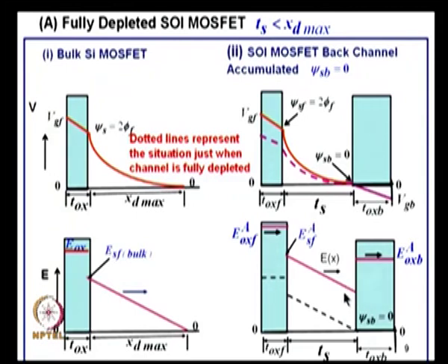I am giving the numerical number because 1000 charges here, okay, 900 charges here, 100 charges coming extra from there. Charge neutrality is maintained. So, this field is not changing, this voltage drop is not changing, but field lines have moved up here.